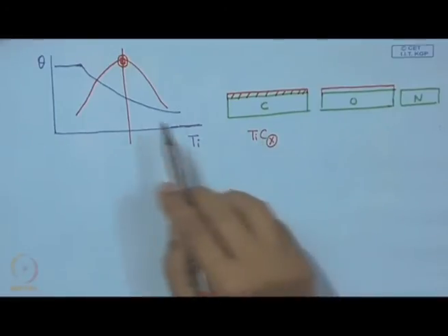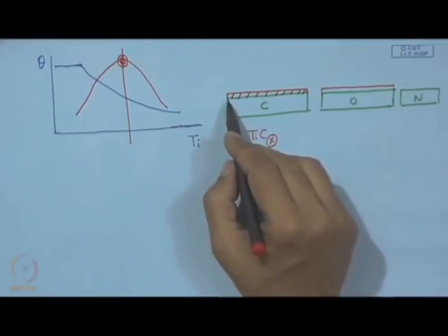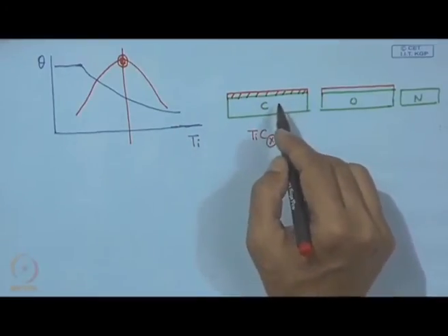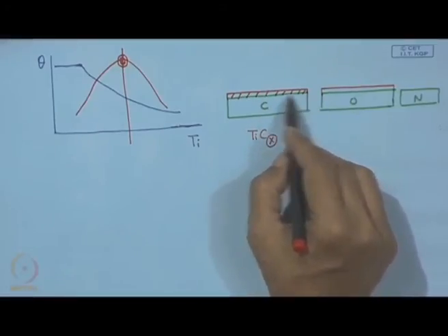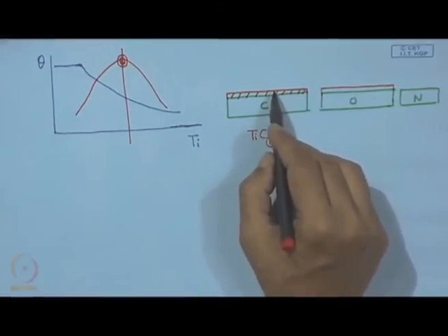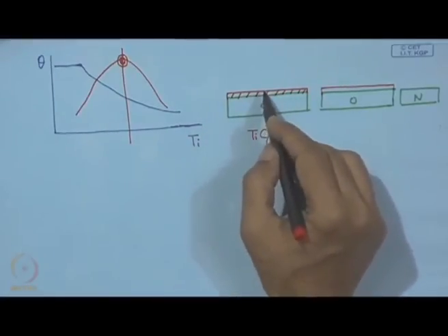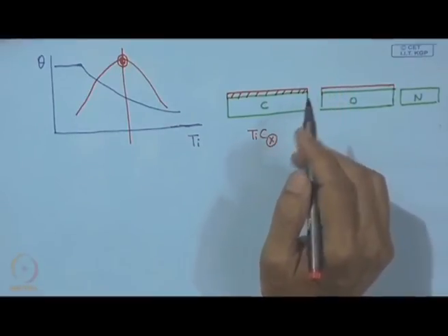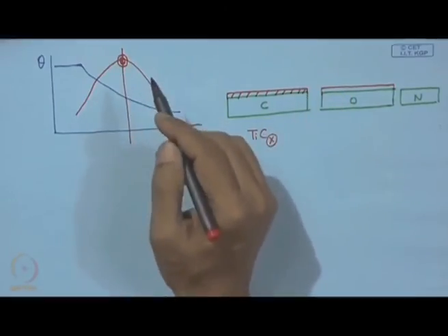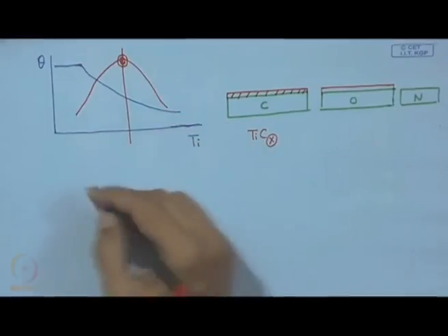That means the sole objective would be to have, in the quickest possible time, a reaction layer which is thin and whose outermost surface is rich in titanium. In that case we can achieve this wettability even with a lower percentage.